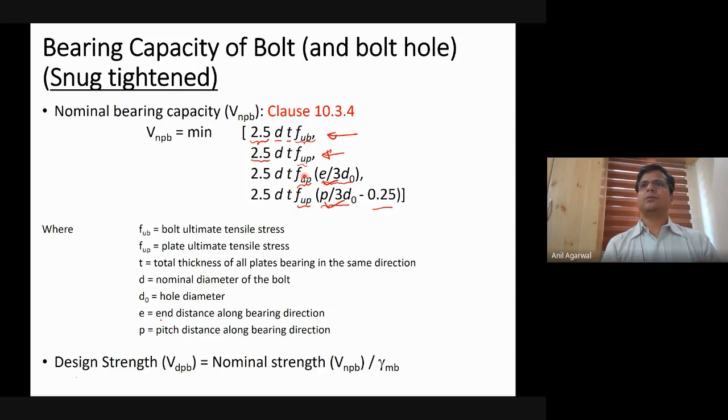More than 50, you may have it, and the corresponding hole diameter will be something like 22. So 22 times 3, actually it's minus 0.25 also. So you have to do that calculation. So whatever that pitch spacing is, you get. So you have some range in between where there will be some interference, and you have to account for it. Got it?